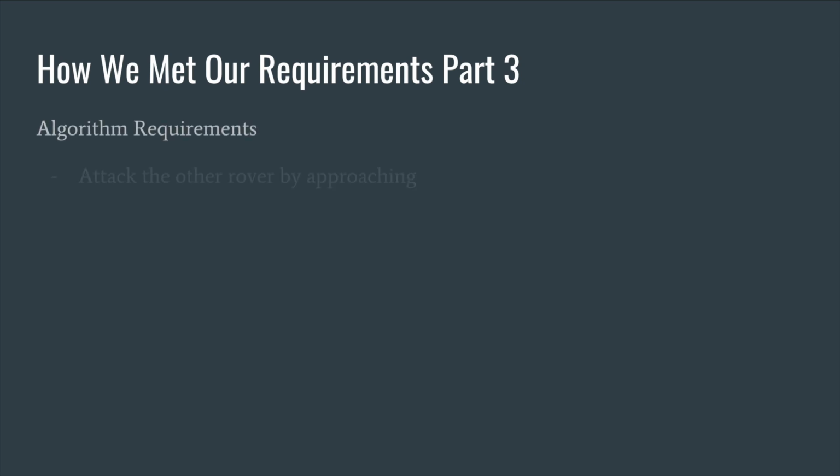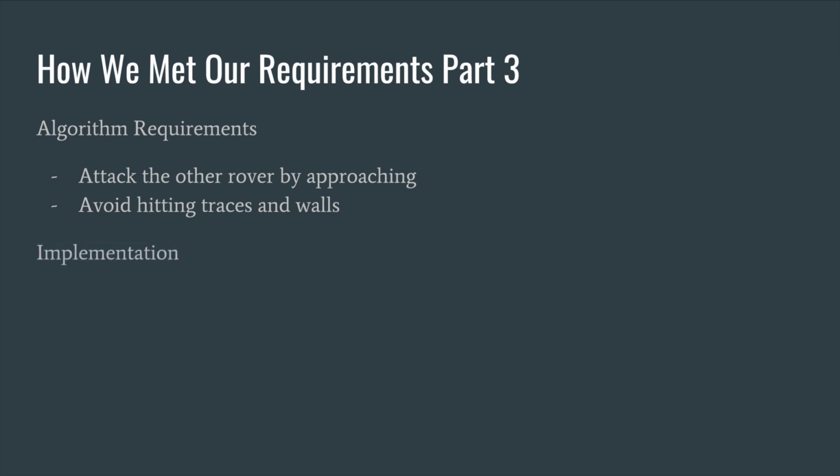The AI rover uses a combination of algorithms in order to intelligently navigate around the play game area. The 2 main algorithms that play the essential roles in predicting the best move are flood fill and minimax. Flood fill helps to visualize the minimum steps that the rover on a certain position on the map needs to travel to an arbitrary point. The algorithm recursively fills up the map by filling incrementing numbers from a certain point to the boundary of the map based on the steps that a point needs to reach another.